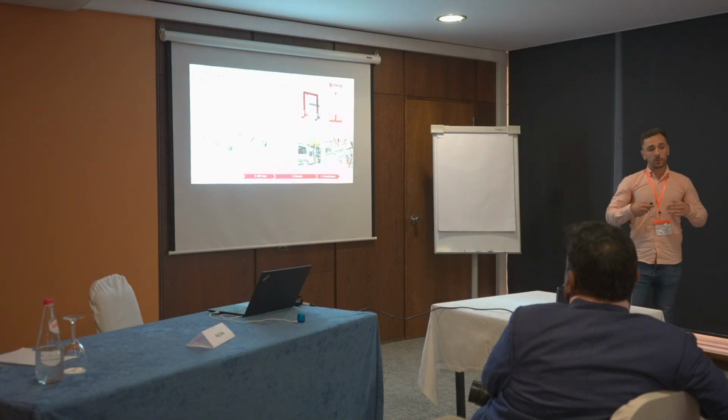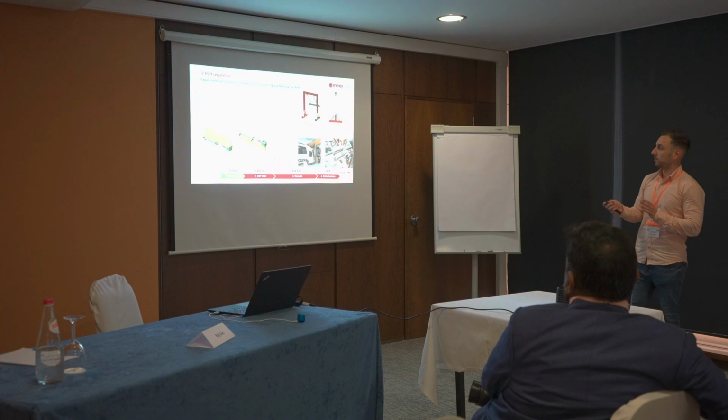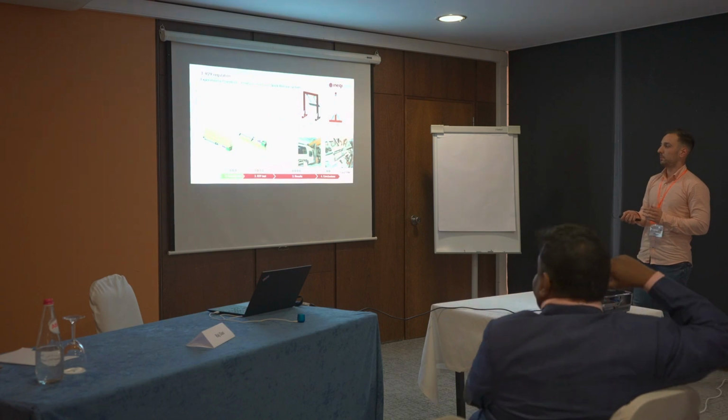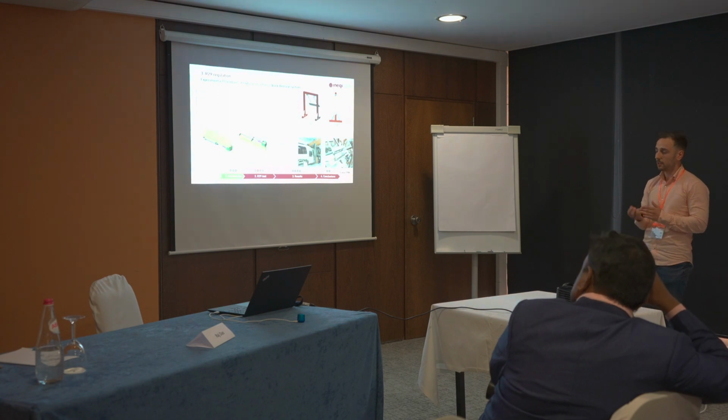It's necessary as well to develop a quick release system to release the pendulum instantaneously. The quick release system is based on a hydraulic actuator. When activated, the pin retracts and the pendulum falls.